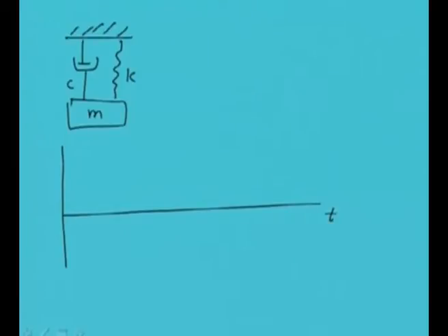Now let us take one example of how to obtain the logarithmic decrement through one experiment. Let us say we have one response which we have measured, the free decay response, damped response, and after the sixth consecutive amplitude we found that the decrease in the amplitude is around 25%. Once we know the system properties like stiffness and mass, how can we get the logarithmic decrement? Let us see through one example. We have one spring mass system, and we have disturbed this system with some initial condition, and we got a response because of that initial condition.